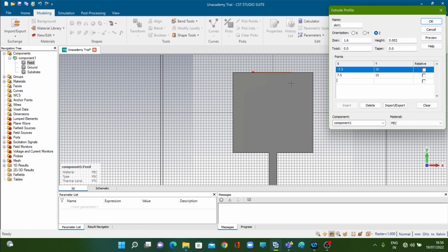Next we will come down like this. If you are coming down, the same horizontal level is maintained, so x remains 7.5. Put tab. Now y is not 15. Y has come down a bit. The point here has a y coordinate value which is less than 15 because we are coming down. Let us take 10. Enter.